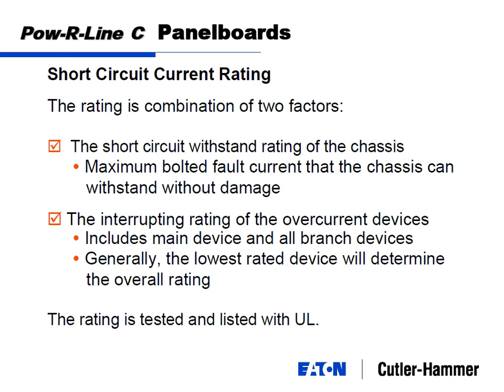Short circuit current rating. We talked about the short circuit, the available maximum short circuit in a facility, that all the devices have to be rated to handle that maximum short circuit. So from a panel board standpoint, short circuit current rating is a combination of the rating of the bus, and